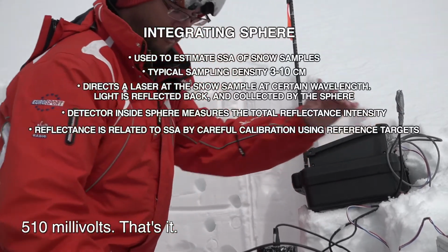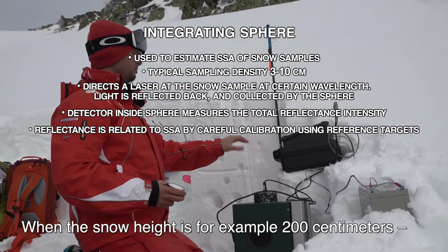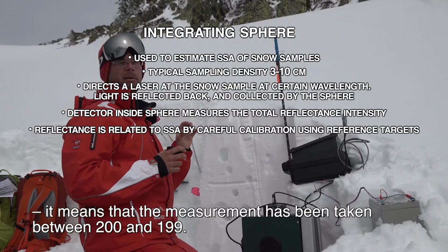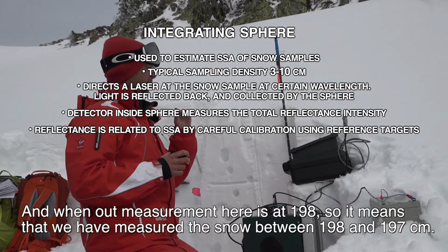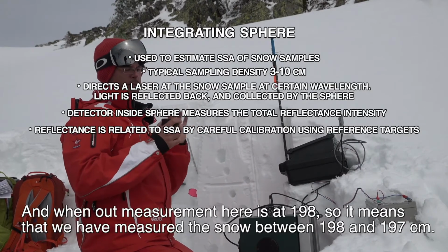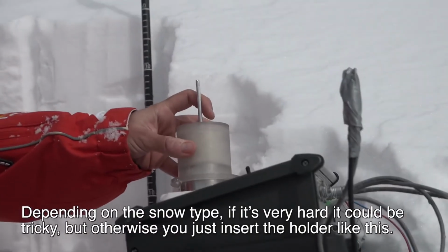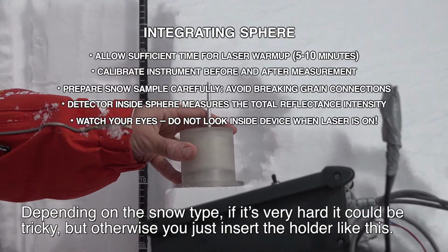That's it. All right. So when the snow height is, for example, 200 centimeters, it means that the measurement has been taken between 200 and 199, right? And when our measurement is at 198, it means that we have measured the snow between 198 and 197. Depending on the snow type, if it's very hard, it could be tricky, but otherwise you just insert the holder like this,